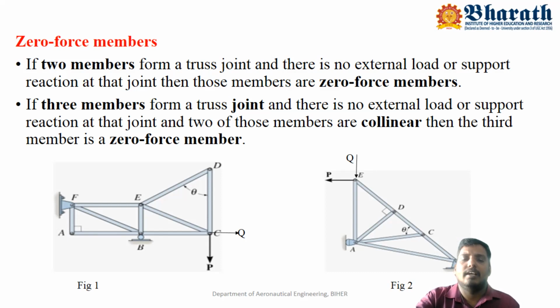While doing the truss analysis, we have made certain assumptions. The first assumption is that all the joints are pin jointed. Loads act only at the joints, and also the self weight of the truss members is neglected.